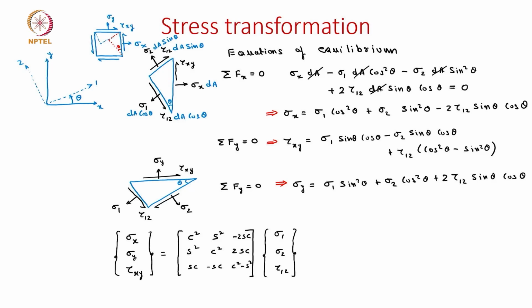But here again I want you to pay attention on this axis or the definition by which we showed the angle theta. So, where is theta going from? Theta is going from the body coordinates to the material coordinates, right. This is what the positive angle theta means. But the way we have derived, we are going from the material coordinates to the body coordinates. So, how do we show that? So, we are interested in seeing the transformation going from the body coordinates to the material coordinates.